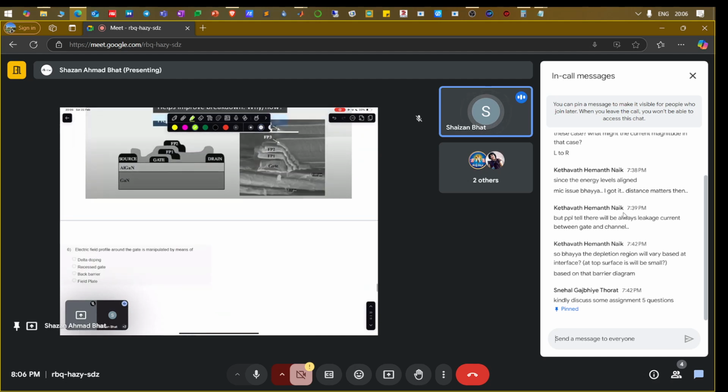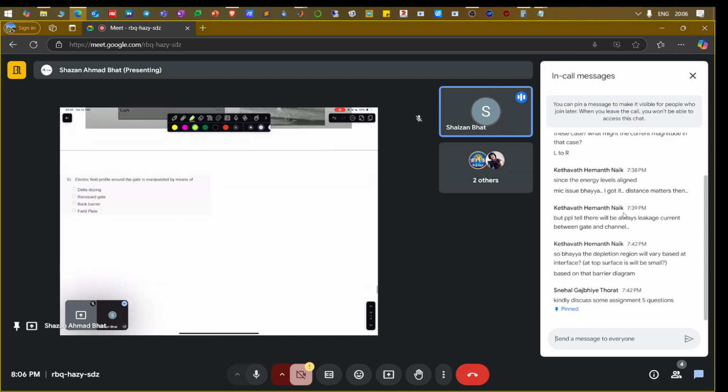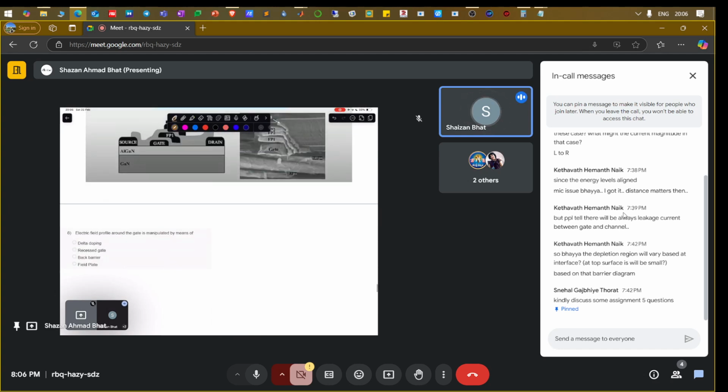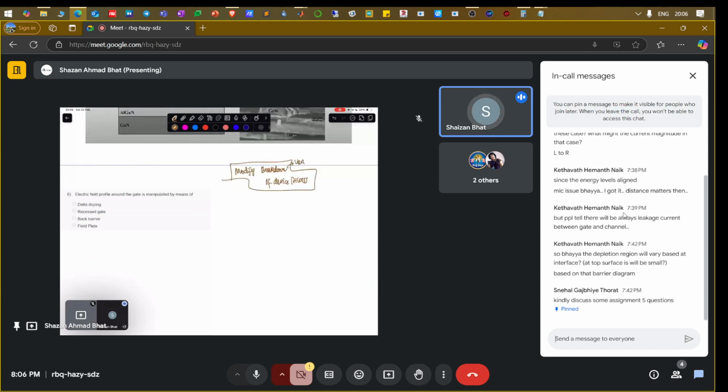But field plates, I guess I have not covered. The field plate concept is something like, if you want to modify the breakdown of a device. Which device are we talking about? HEMTs. So if you want to modify the breakdown voltage VBR of the device, you use something called field plate technology. It's just like using multiple gate plates over one another with certain dielectrics.